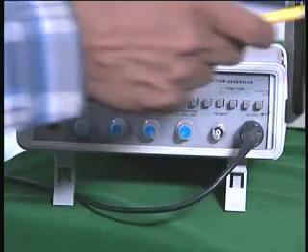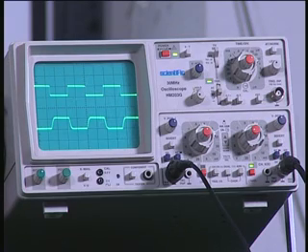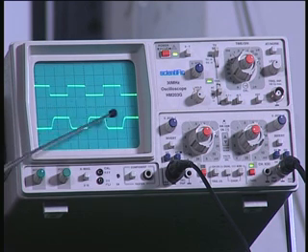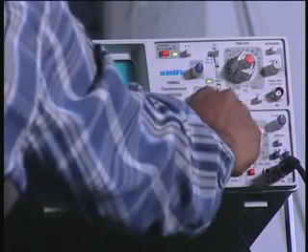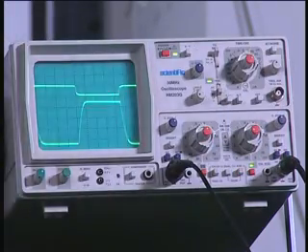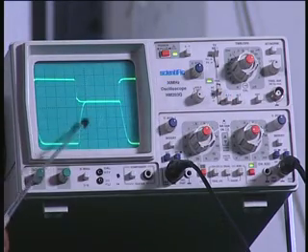You can see on the oscilloscope, this is the input square wave where the vertical line is almost not seen because it is at the input, whereas because of the slew rate at the output there is a finite slope. So you can see the sloping lines. If I now increase the gain, you will be able to see the variation much better. So you can see that this is not instantaneously going to high, but with a finite slope.